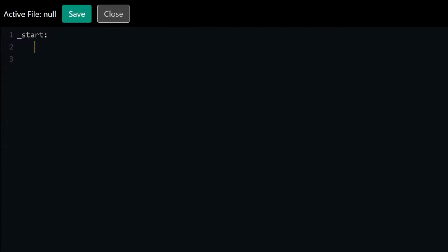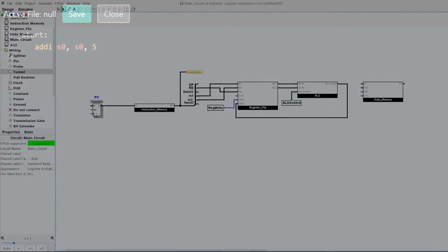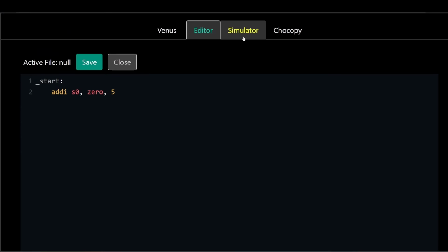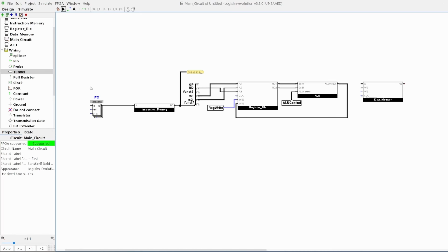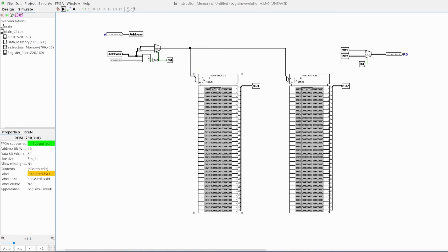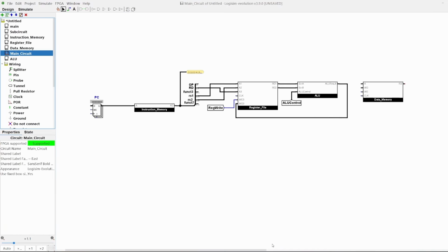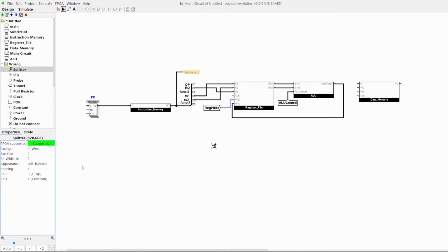If you remember from our previous video, we choose addi to set the value of a register to a number. So let's add those I type instructions now. For an I type instruction like this one, we can again put it into our instruction memory as before. For I type instructions, the instruction format is different from R type instructions. Most things stay the same, but we have to combine our last 12 bits together to get our immediate.